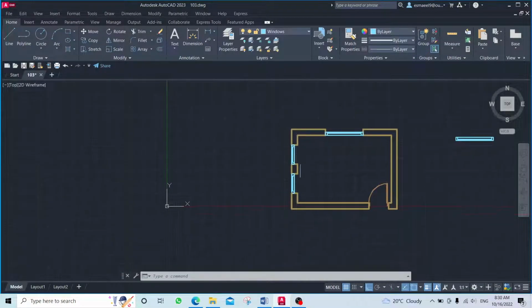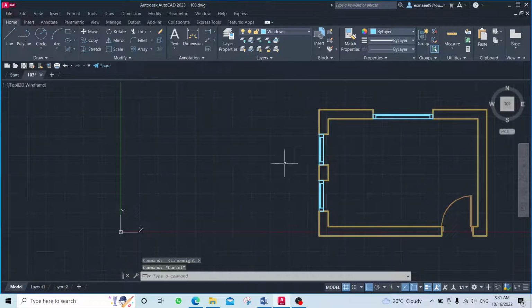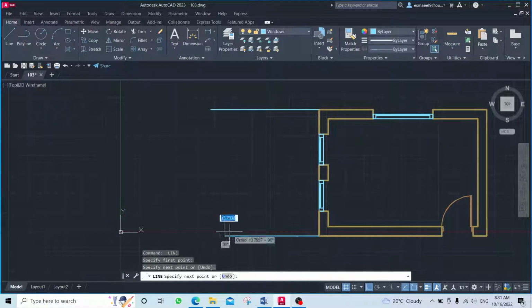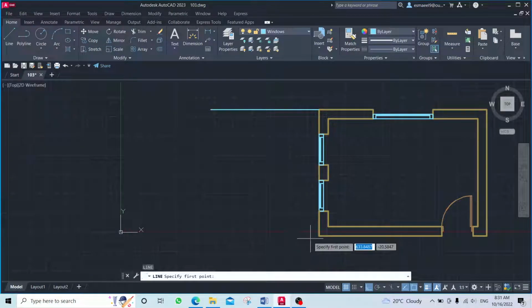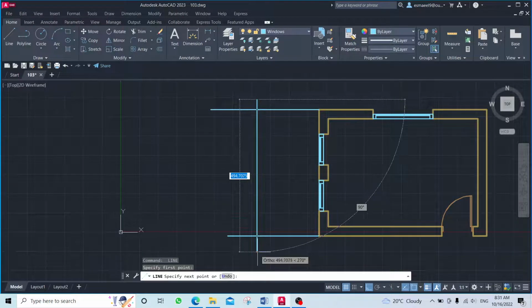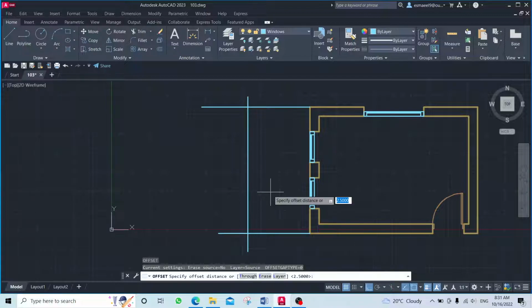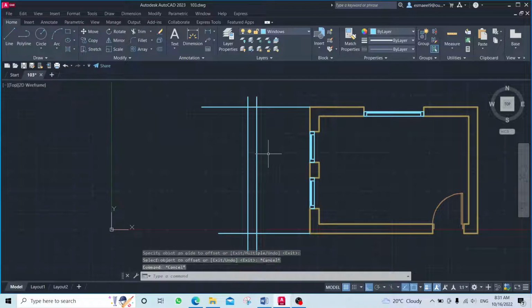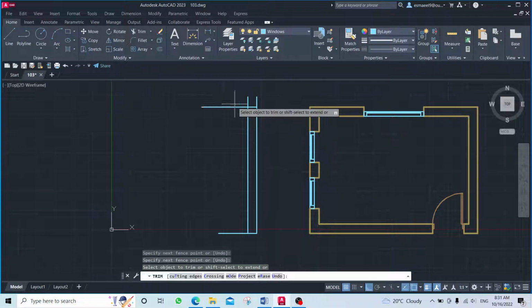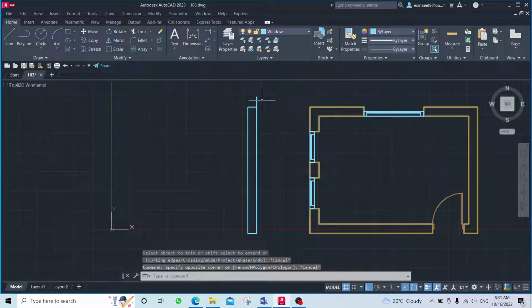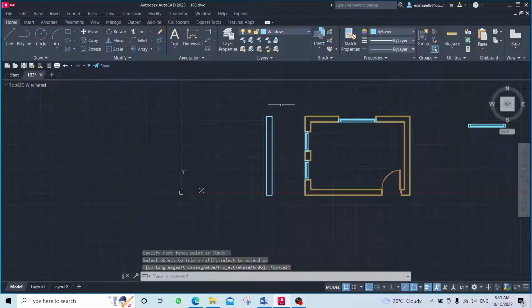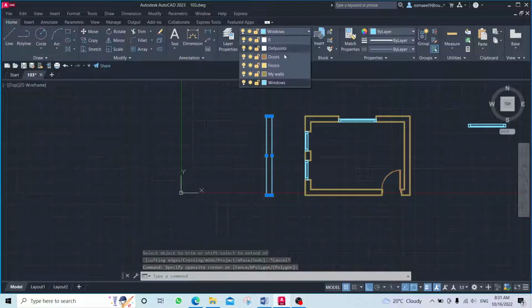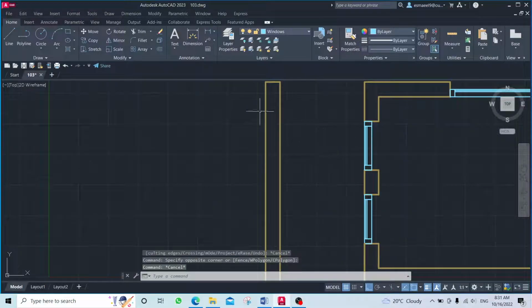No need, I think, to explain how we created it, but even though I will repeat this wall only. So let's say I will just create the same thing. Let me delete this one to make it horizontal and make another line and then offset it by 30 centimeters, and then delete the others. So as you see, I created this wall with a different layer. I could directly select it and select all the layers now, and now select your wall. So it became a wall layer.